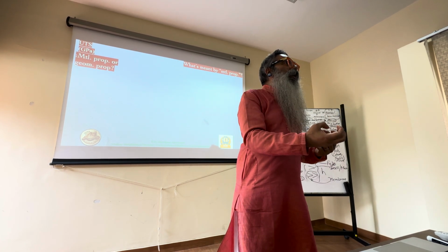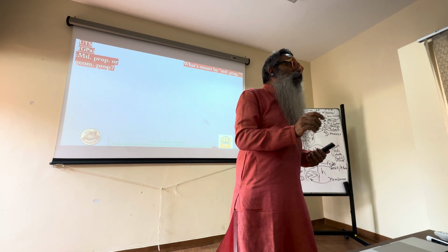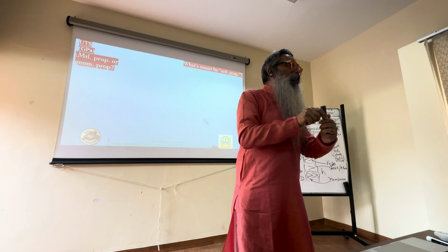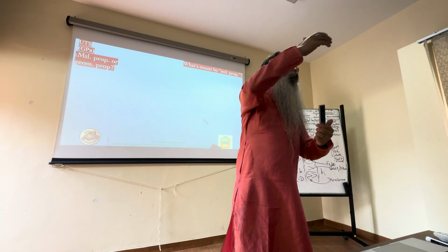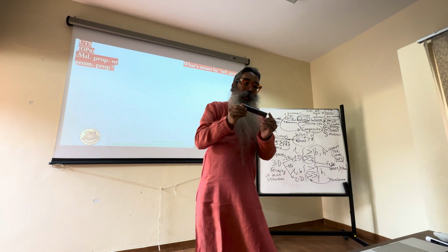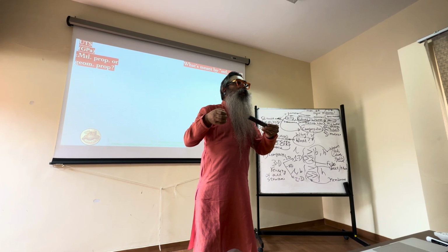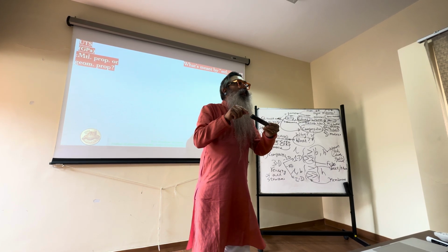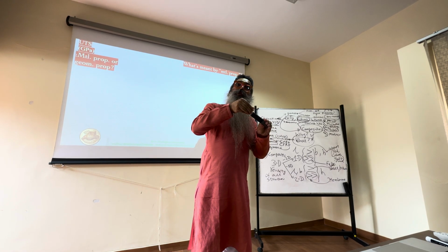So therefore, there are certain standards defined by entities like ASTM, which will give you a particular shape. The reason for that dog bone shape is the Saint Venant's principle that we discussed in the beginning: at the boundaries, the way the boundary conditions and loads are applied will affect the stresses in a local region, which is of the same order of magnitude as the size of the cross section.